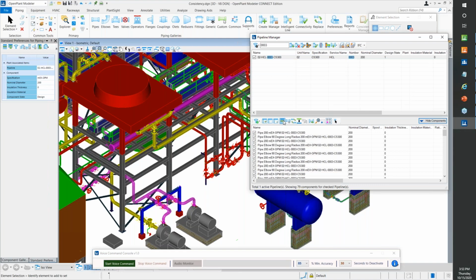So automatically the system will give the list of variations, and the engineer's work is to accept it and go ahead according to the spec revisions. So these all are inbuilt over here. And at top you can export all this pipeline data to different environments. Let's say you can generate spool IDs, you can export data to stress analysis, you can do the consistency checks over here, as you see here, and so on.